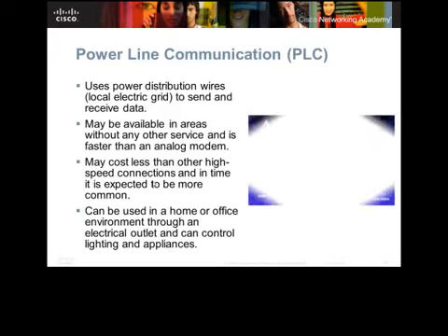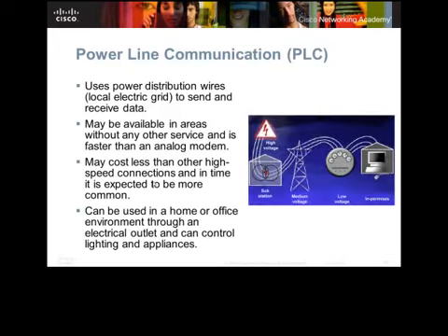Powerline communication, or PLC. Powerline communication uses our power distribution grid to send data signals along with our power across the existing infrastructure. This is kind of a newer technology that's still kind of in its infancy. We probably don't see it a whole lot out there right now, but we will start to see it more and more often. Because of the existing infrastructure, we can potentially offer internet connection and data connections to places that